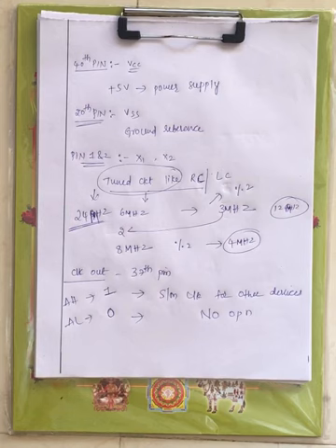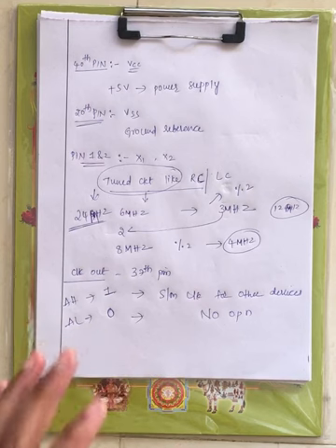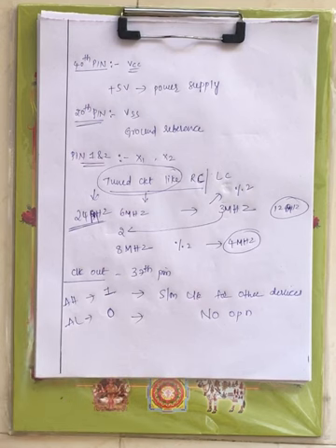A tuned circuit like LC or RC or a crystal is connected at pin number 1 and 2 to provide the oscillator frequency, and the internal clock generator divides it by 2, which gives the operating frequency of the processor.